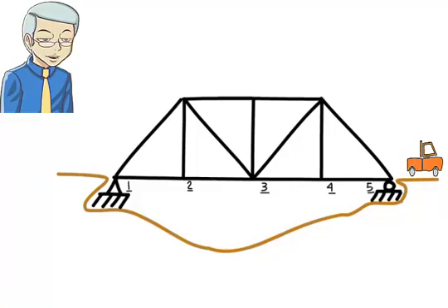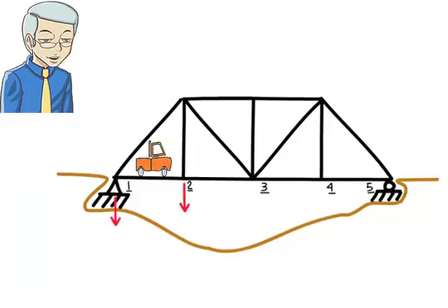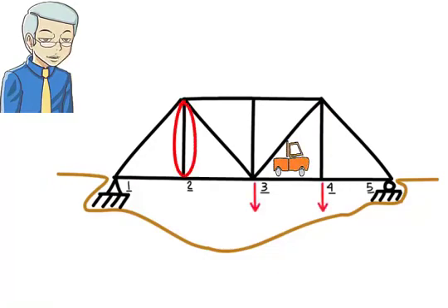Note that a truss member that actually carries an axial force in one loading case may become a zero-force member in another loading case. For example, when the load is applied at joints 1 and 2, the vertical member attached to joint 4 carries no internal force.